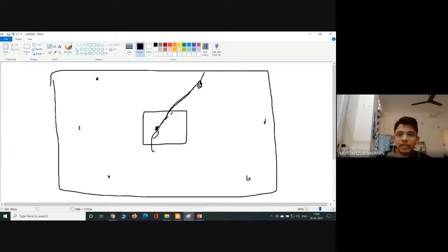That distance will be converted into a suitable map distance with the help of a scale, 1:50, 1:100, 1:500, whatever is suitable, we will use that value, and we will draw a map here. So in the ground, this is our A point, say for example, this is our B point. In the map, this is our A point and this is our B point. Like this, we will draw.